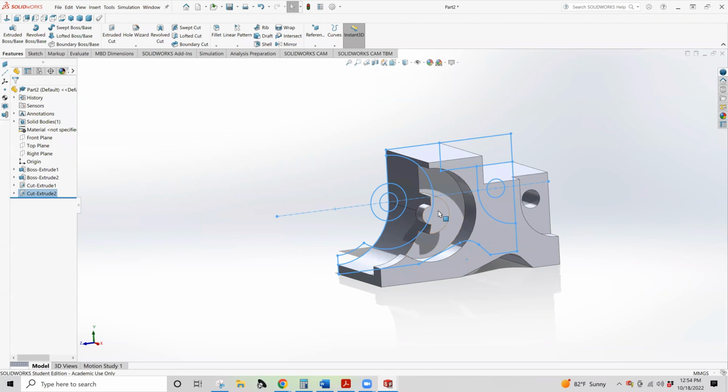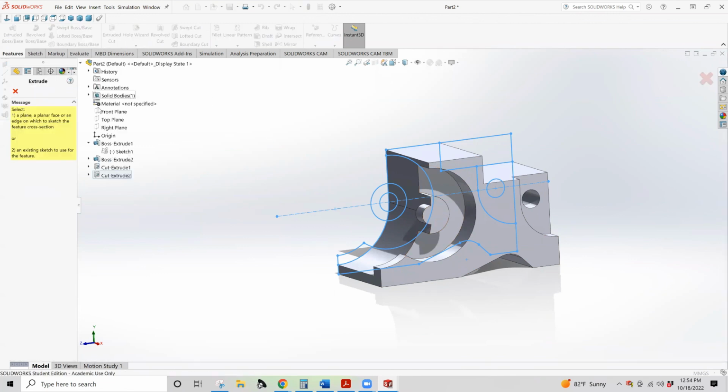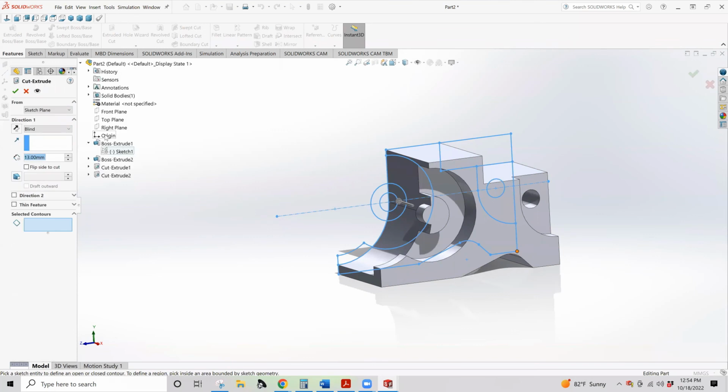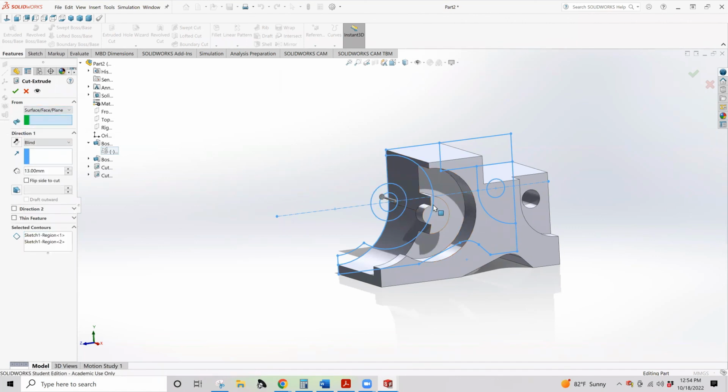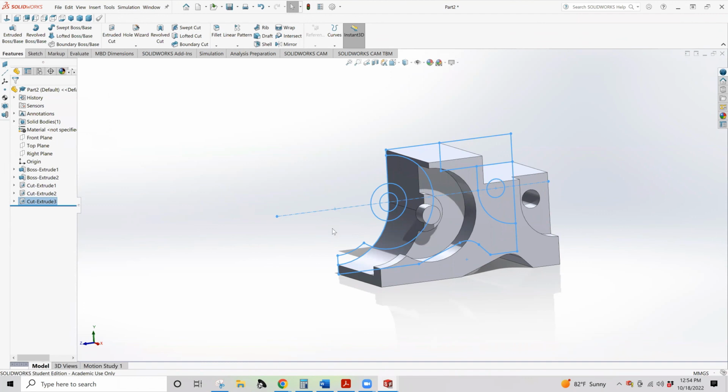Then we're going to do another cut for the second step. So you want to kind of think in terms of operations. If you were to go in, you would have to change drill bit sizes and things. That's kind of the approach that you're going to take. So we're now going to take these two from the surface, from this surface, and it's going to be, instead of 13, that same 8. So that same 8 cut.